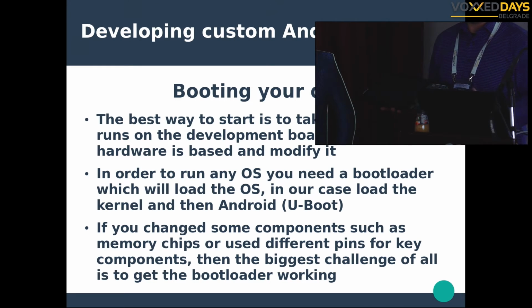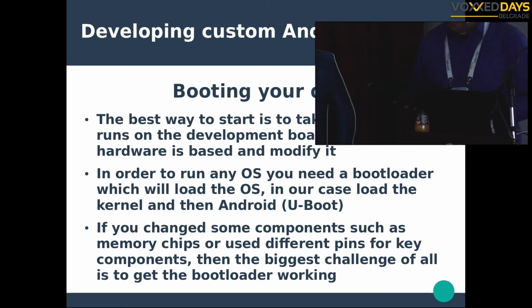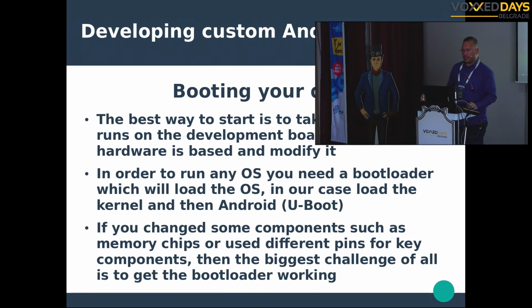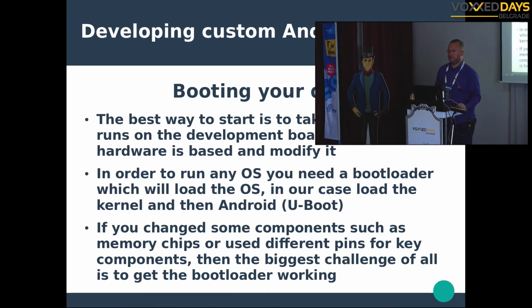So if some part of the code is working, we put, okay, turn on the LED, and we see, okay, the code progressed to this point, so something is working. If you change the specs of the development board, you change some pins, you change some key components or stuff like that, probably you will not boot the bootloader initially.